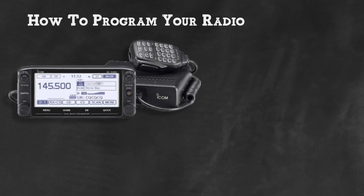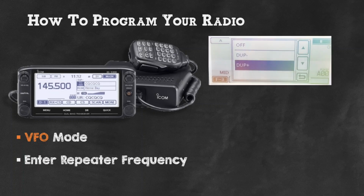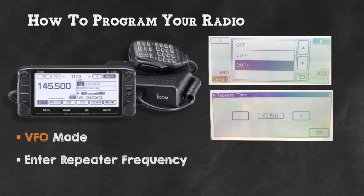Now, if I look at my radio, which is a higher end radio, like a 50-watt mobile base station unit here, again, same principle. I have to go to the VFO mode and tune in the frequency. Get to the right frequency, and then I can start programming it. It automatically calculates the duplex. Is it a plus or is it a minus? I can hit plus, or if there's none, I just do 0 on it. Repeater tone: essentially, do I do plus or minus, up or down?